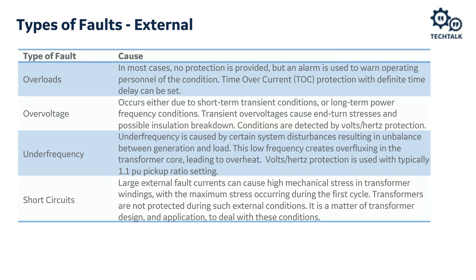Even though short circuits can cause mechanical stress within the windings, we typically do not employ short circuit protection specifically within our transformer relay for the sake of having proper selectivity of our protection scheme. The transformer is usually sized accordingly to be able to deal with a short-term short circuit, and we depend on our other overcurrent relays to clear it.